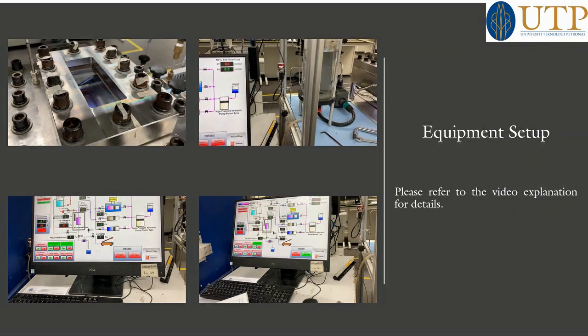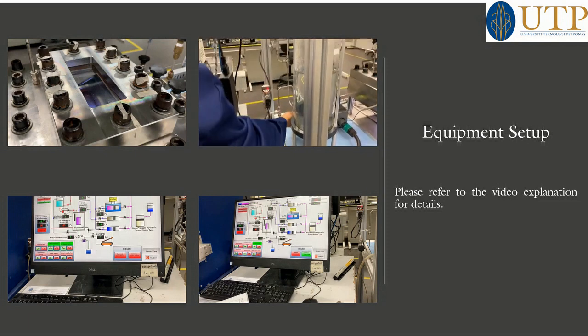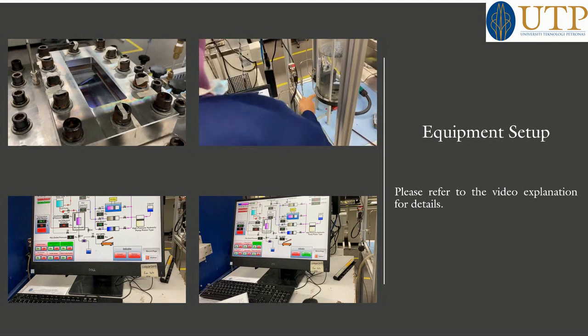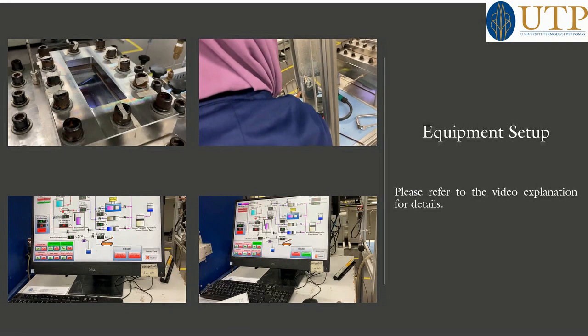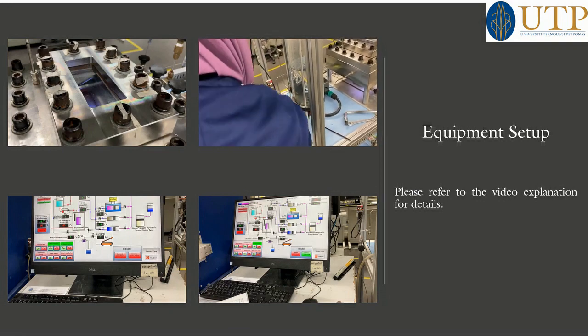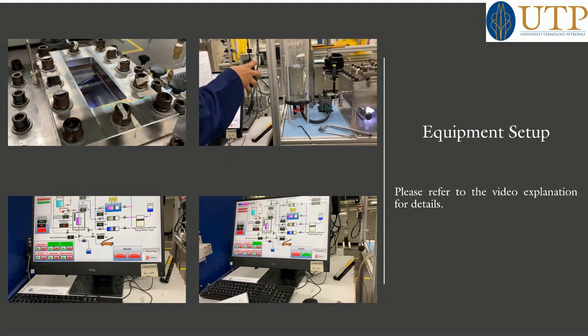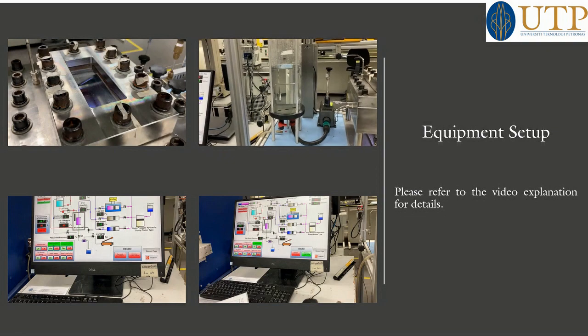This is the V11. So change the direction of V11 towards the water tank. So I change the position of V11 towards the water tank. That means it indicates that it will take the water from this tank. And click motor reverse button and high speed button.